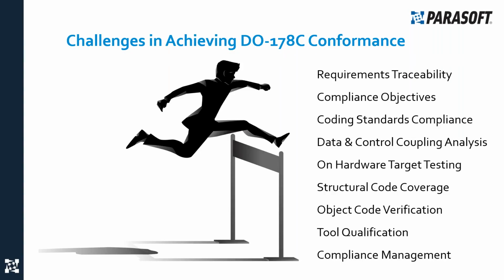Also, perform structural code coverage to ensure that you've tested all of your requirements. Also, you may need to perform code coverage at the object or assembly code level. Use a tool that has been qualified in the past and that has a tool qualification kit available to automate this qualification for use on the development ecosystem that you have. And finally, have a compliance management plan and expert DER that can help you through the certification process.